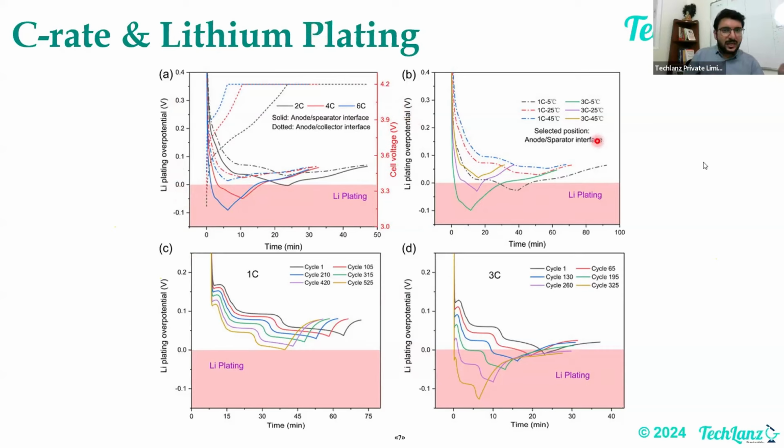It allows a very fast pace of movement of those ions. Graphite is a 2D, layered geometry, so you can only move one by one. Imagine two parallel plates and you're trying to insert a ball inside, one by one. That's the mechanism. That's why LTO supports very high discharge and especially very high charge rates. Okay, not diluting the topic, coming back to this again.